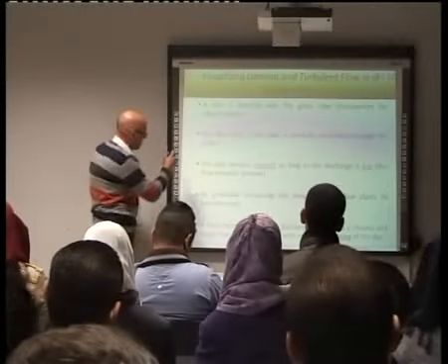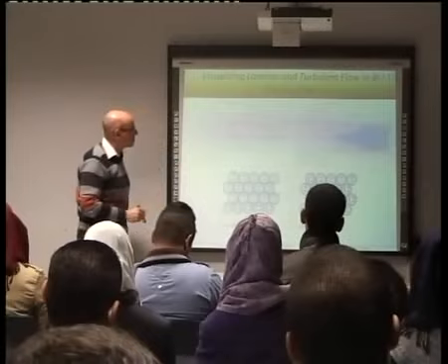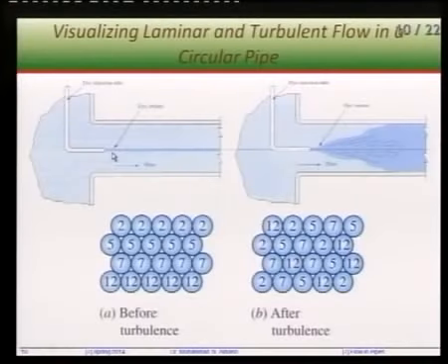So this is the situation. This is kind of laminar flow. You see, this remains on the same path, this remains on the same path, and the dye will not get mixed. This is laminar flow. But if we look at this one, now because we have increased the flow rate by increasing the opening of the valve, then mixing will start.